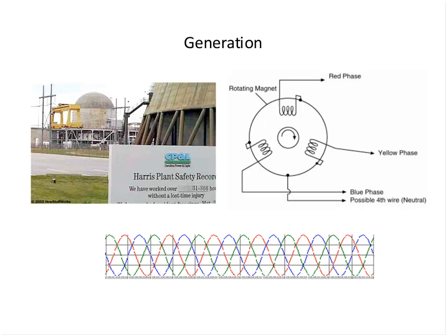And the reason why we pick 3 and not 2 or 4 is that when you do 2, you have multiple times when the voltage goes to 0 if you have 2 phases. In a cycle, just think how often you'll hit a signal going to 0. If you go to 4, you don't really add much in terms of continuity of power. You know, the marginal utility of adding an extra coil is less.